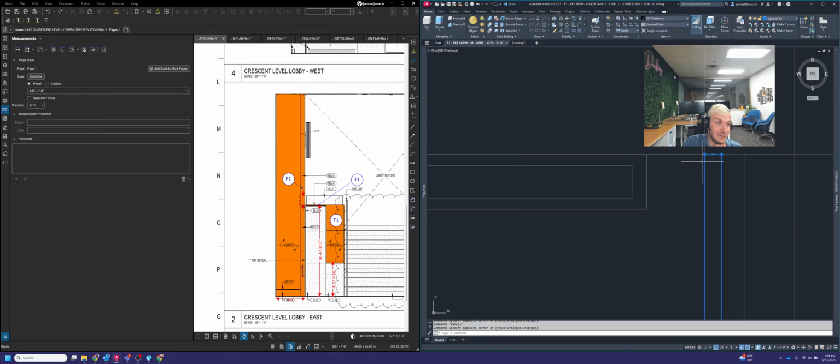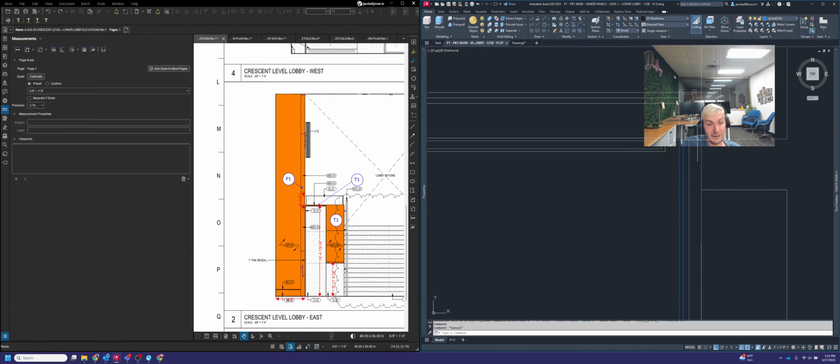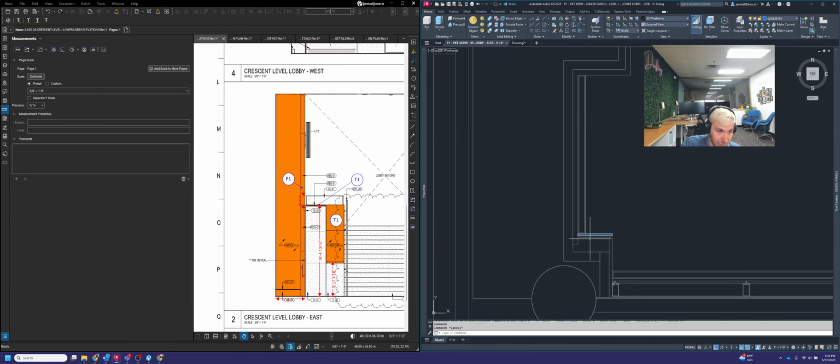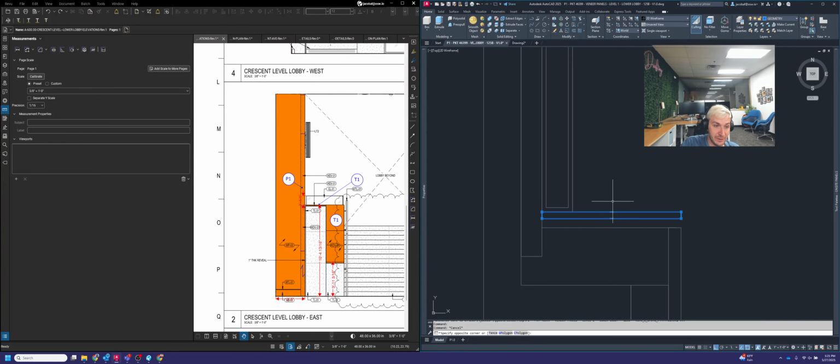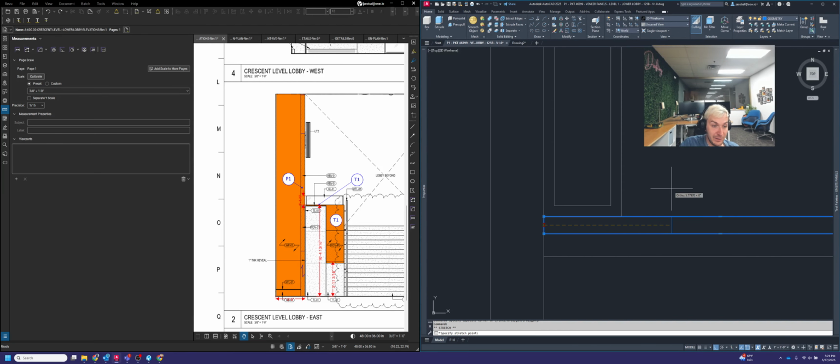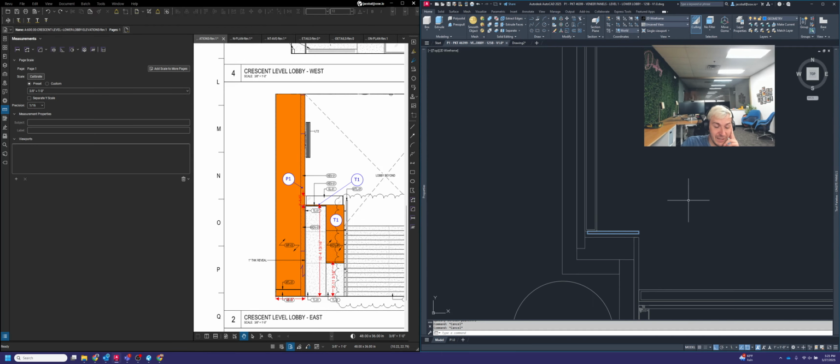It's 23 feet tall, so really you want to make sure that you have a gap here. We're going to make this 3/4 of an inch, and we'll put a full depth reveal here between this wall and the start of our panel. We're going to do the same thing over here as well, because here you've got a panel butting into a wall right here. And really, you can't really do that. I mean, you can, but it's going to be a real pain. So we're going to shrink that a 3/4 inch to make sure there's a 3/4 inch gap right there.